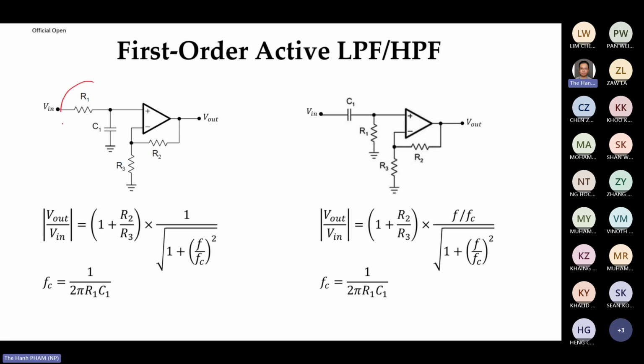This one is obvious from the passive filter. This one is the low pass filter, right? This part is doing the filtering, and this part is providing you with the gain. Now why? Because can you see, if I forget about this portion and only look at this, and here I have a V, this one is nothing but just a non-inverting amplifier, right?